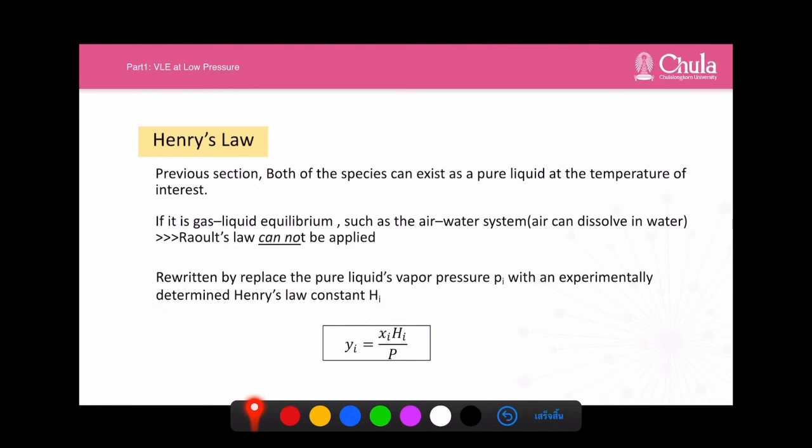So you see that for the non-condensable phase, the concentration is very small, so we can approximate the condensable component's concentration as a pure component. So for pure component, gamma is equal to 1, okay? So the model is yi p equals xi Hi.